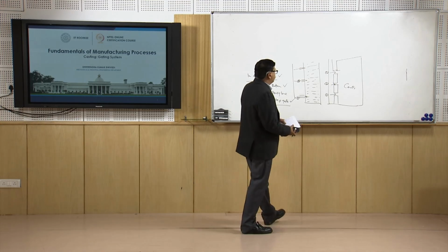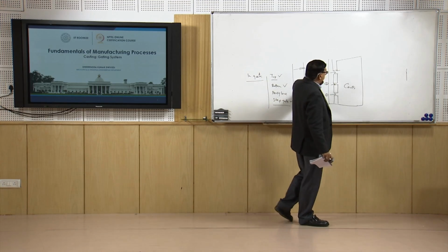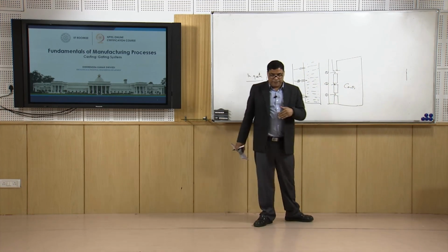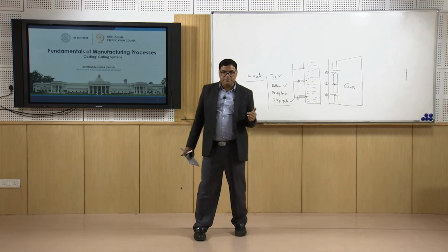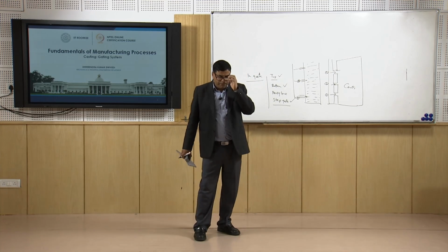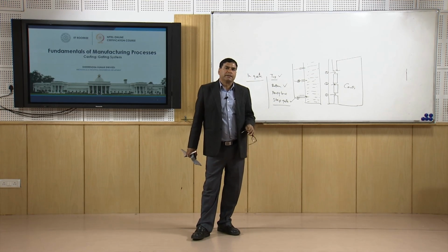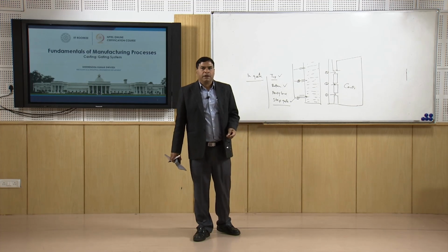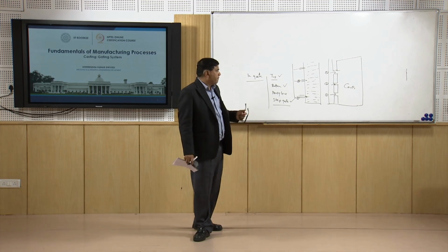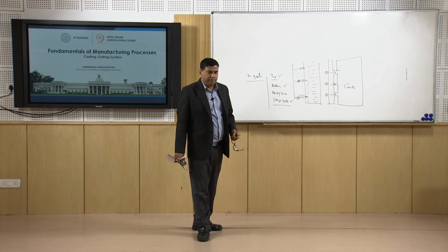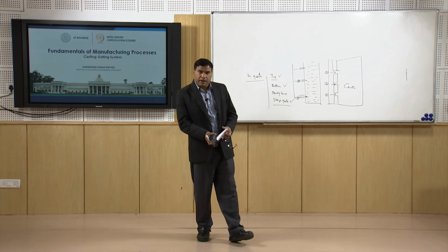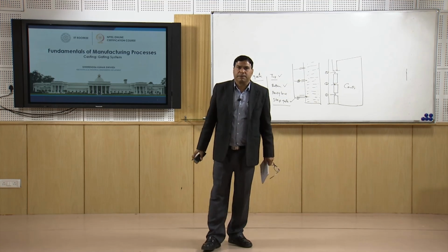So, the purpose of having a number of gates is to fill large size cavities in the minimum possible time, while also having the favorable temperature gradient. So, here I will now summarize this presentation.